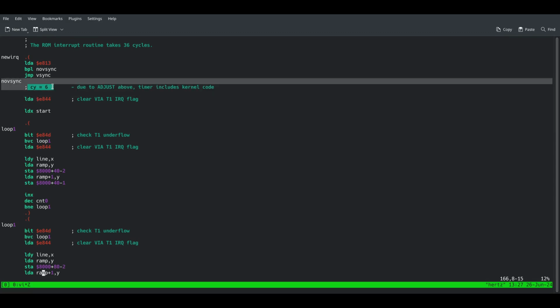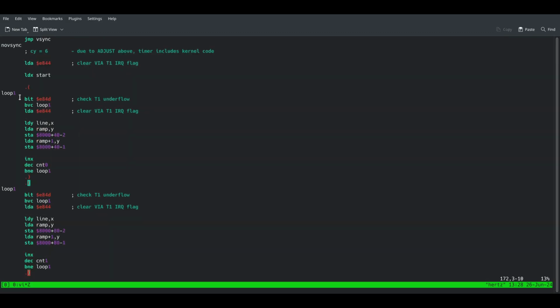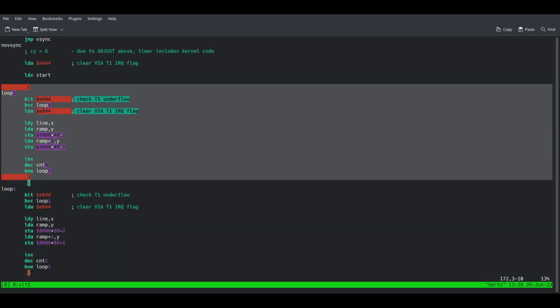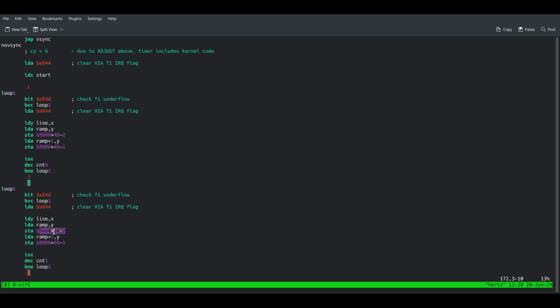In this here, the routine jumps into when the VIA timer fires, so that we had the vertical sync timer, and then we had this offset until the raster line where the effect actually starts. We clear the interrupt flag, and then we actually have a number of those loops. I didn't do a full loop unrolling, but I have a loop for each character line, because in the character line this value stays the same. You can see here it's plus 40, it's plus 80, and so on.